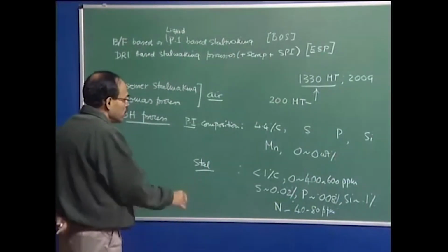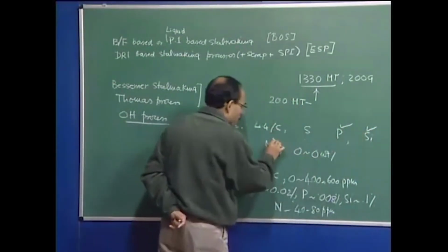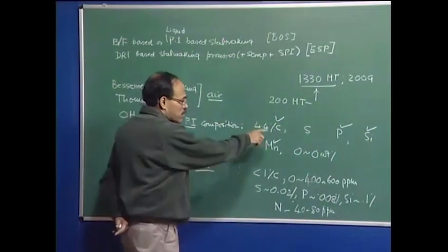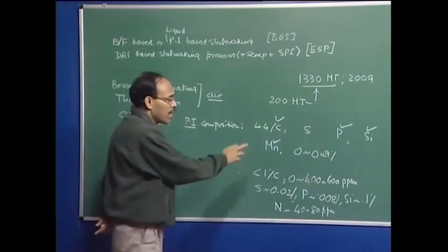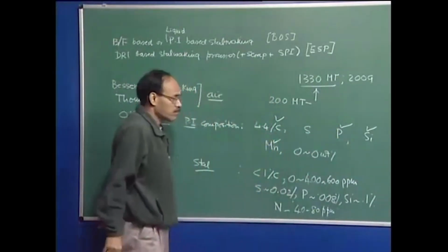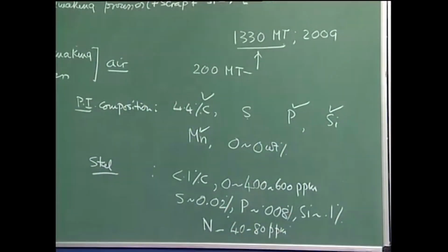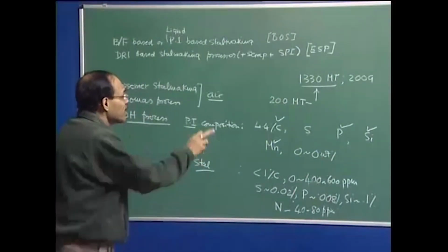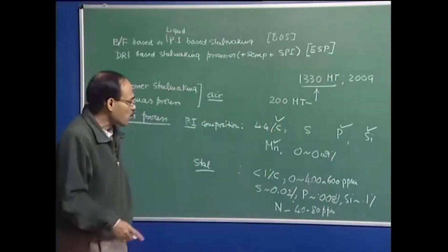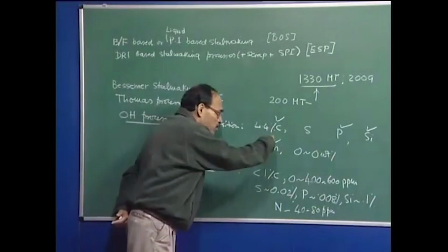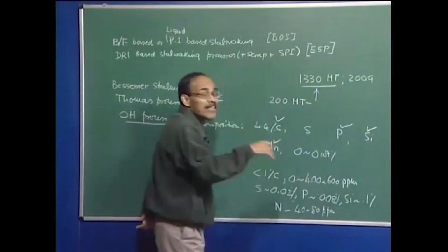So, to remove, as you see, phosphorus, silicon, manganese, carbon, you will study this in detail in the principles of steel making. They have higher affinity towards oxygen. We will also see in the Ellingham diagram that I will discuss when I talk about the science base of steel making under the section of thermodynamics, these are the elements carbon, phosphorus, silicon, manganese. They have great affinity for oxygen, and that is why when you pump oxygen through molten pig iron, this element reacts with oxygen and gets oxidized.